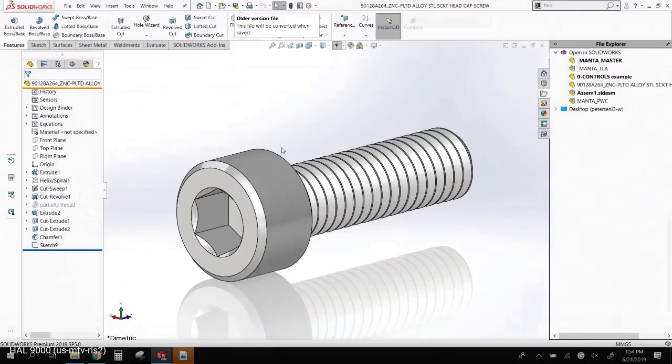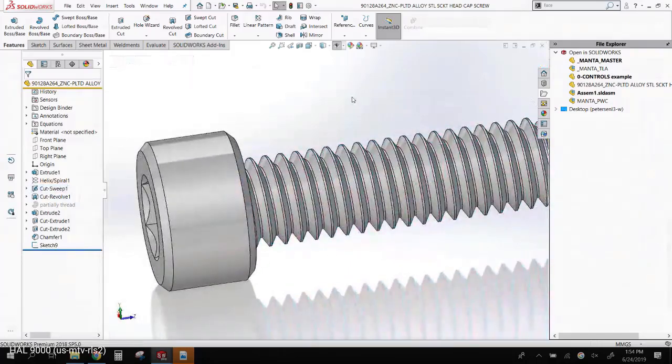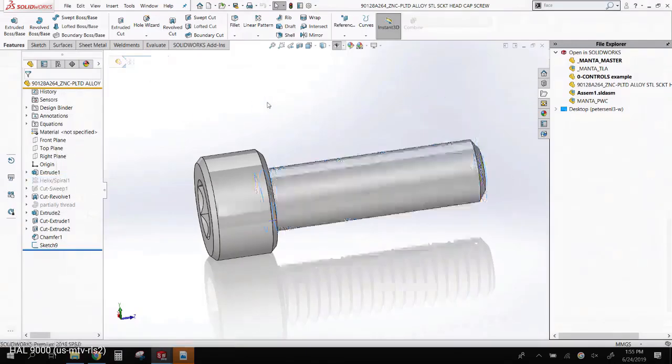Do not save this to the vault yet. The number one thing I was talking about, graphics is usually the problem when SolidWorks is hanging up or taking a long time. One bolt inside an assembly is not going to shut down the whole works. But if I have 100 of these bolts and they're all mated in place, and then I switch to wireframe and it's got to draw that helicoil for 100 different things, my computer has just frozen. And now I can't rotate it. It's just locked up. So please do not save these into our vault. Just suppress the helix. There we go.